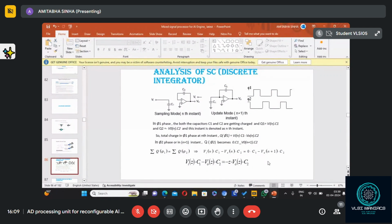This is in the next instant. These are discrete systems. If I call this the nth instant, then this will be the N plus 1th instant. If I call it the N minus 1th instant, then it will be the nth instant. So here we have VIN into C1, that means in the nth instant, the voltage on this capacitor minus V0 into N into C2 will be equal to 0 into C1 minus V0 into N plus 1 C2. It's simple. That means total charge in phi 1 is equal to total charge in phi 2.